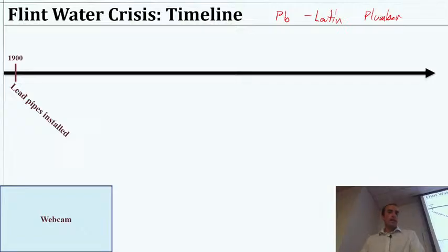However, it's actually also the case that it's potentially okay to have lead in the pipe so long as you're doing everything else correct to prevent that lead from coming off of the pipes. That'll be a big theme today. It's not actually the case that lead is always a risk. It means if you have lead in the pipes, there is a risk, but if you manage your distribution and your water quality properly, maybe it's fine. Okay? Even though there's still a risk.